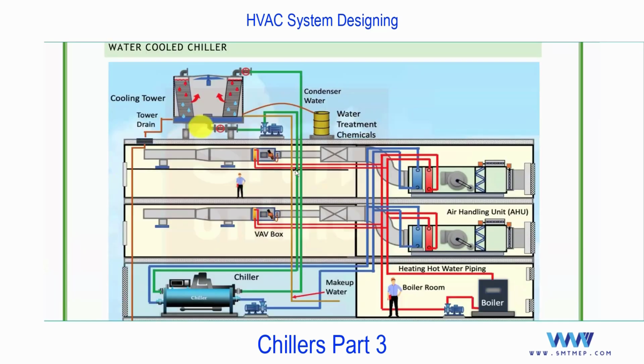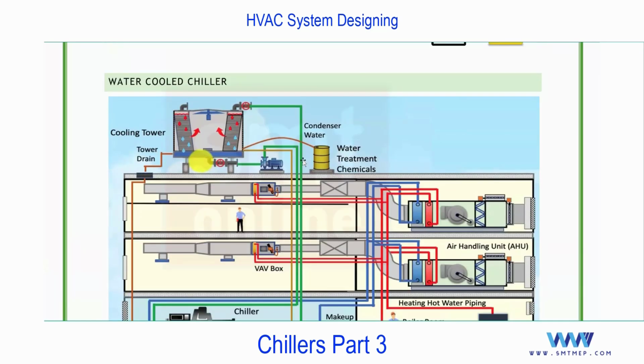Apart from this, you see one more point related to this water cooled chiller. We require this dosing plant also if required, if the water is not potable water. It means a separate treatment is required to maintain the quality of the water, so that it will not decrease or damage the system. Okay, in some projects, we need soft water, right?